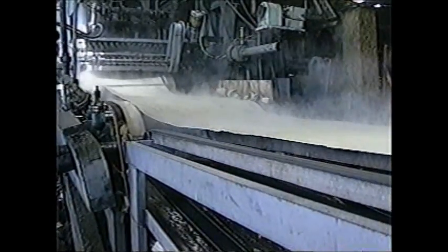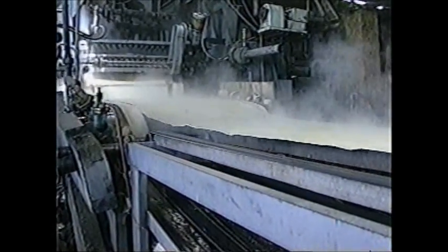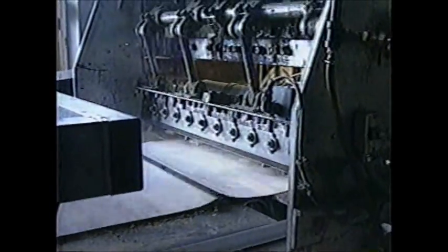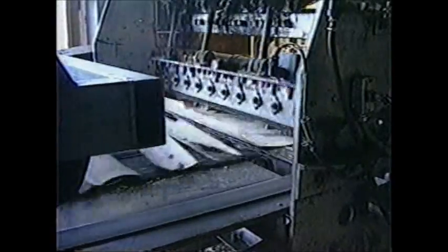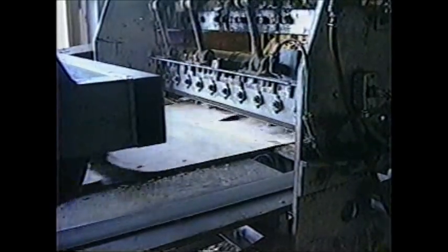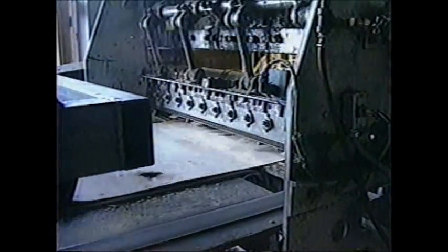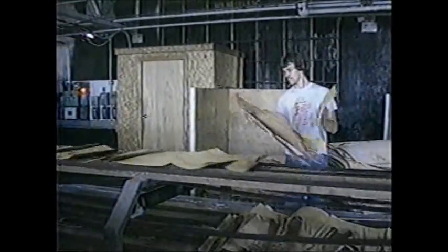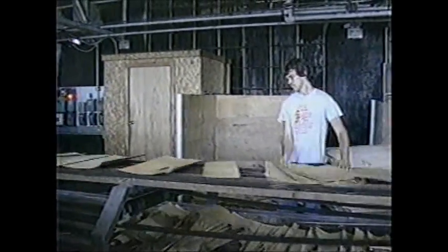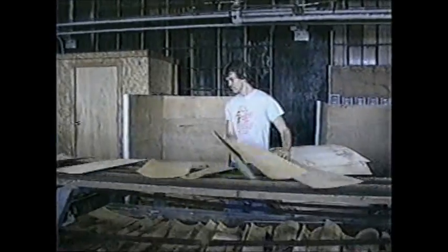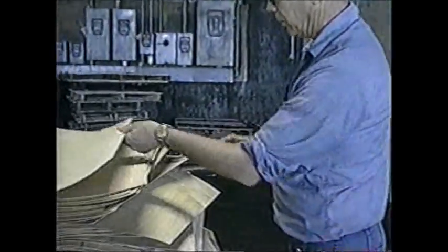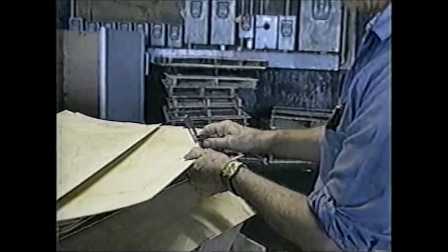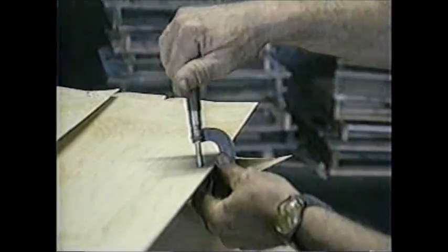Once satisfactory veneer is being produced, it passes through a computer-controlled optical scanner and clipper, which cuts out open defects above a specific size and cuts the continuous sheet into standard lengths. Trimmed narrower material is cut into random lengths. The standard and random lengths of usable veneer are sorted and removed from the production line. The veneer thickness is constantly monitored as part of quality control.